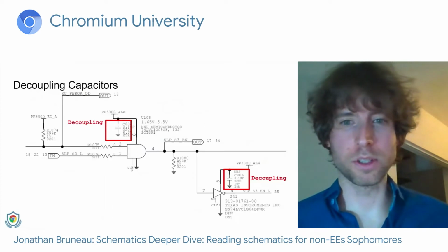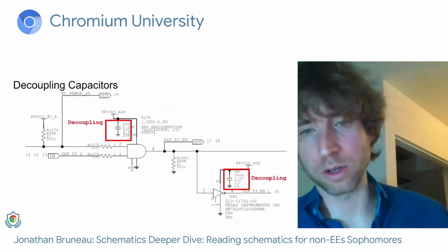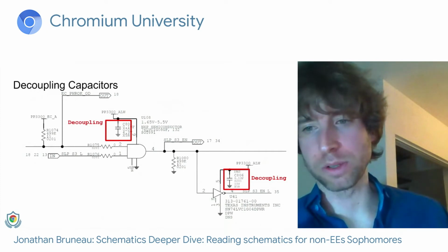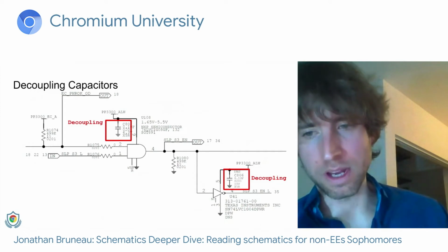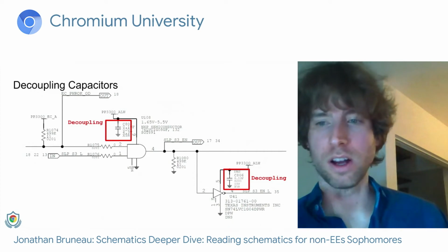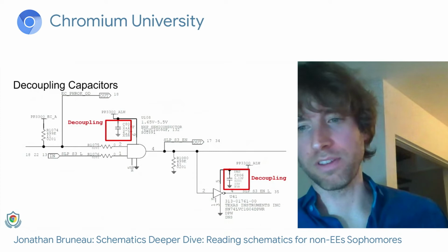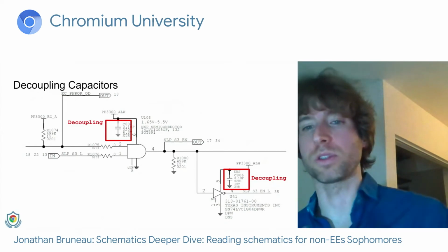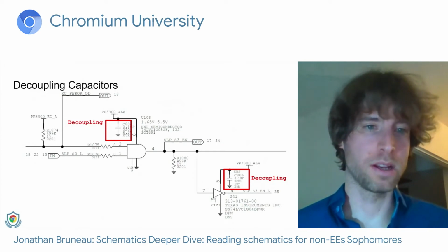Okay, so when we add these capacitors, it's a little battery close to the logic chip, so that when we have this immediate low to high response, all the electrons that are missing can be fed right from that capacitor right there. And then the battery has more time to fill the capacitor again.